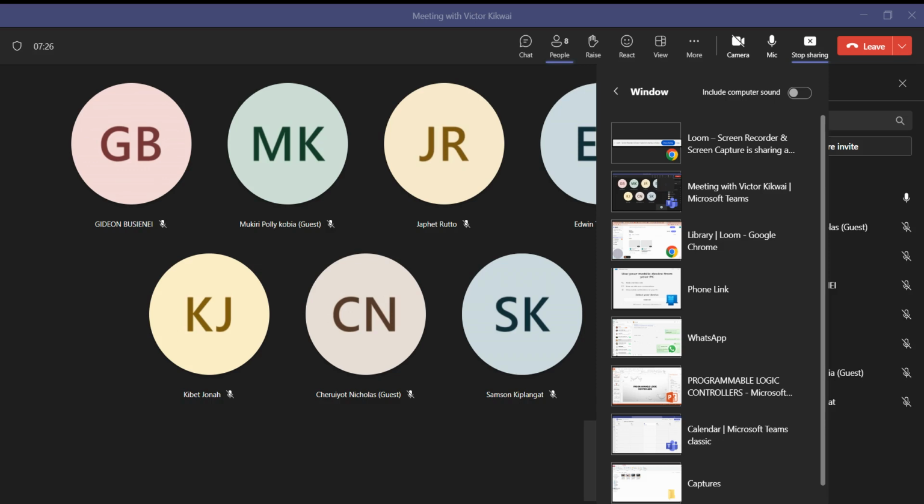Next we are going to look at the architecture of a PLC. PLCs have three main modules in any general PLC, excluding some specialized PLCs that may have other modules, which we are not going to look at the moment. The main three modules are the CPU module, the power supply module, and finally the input output module.